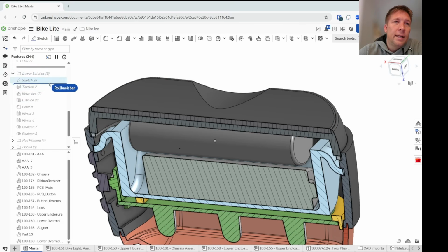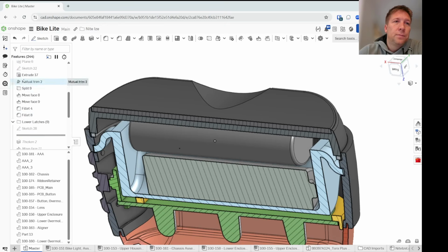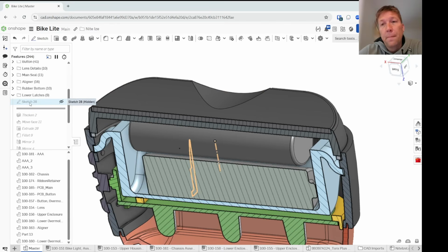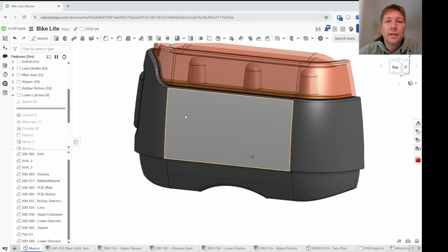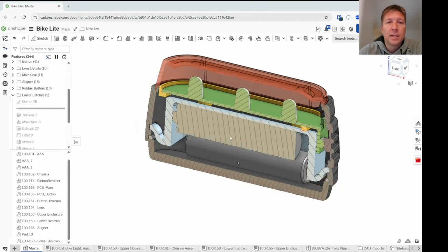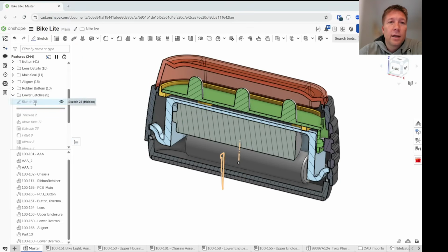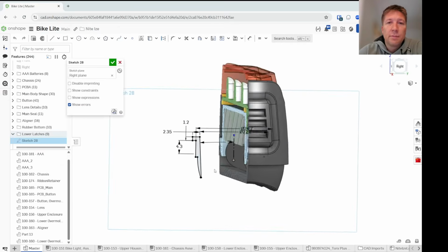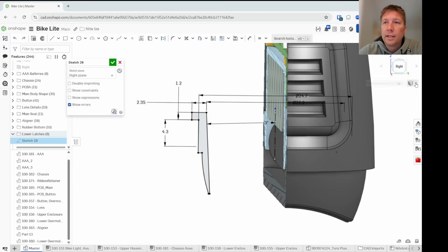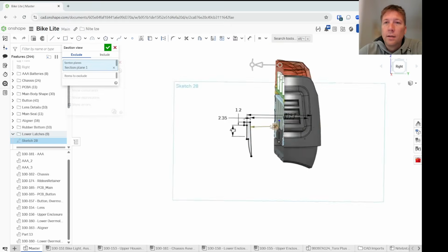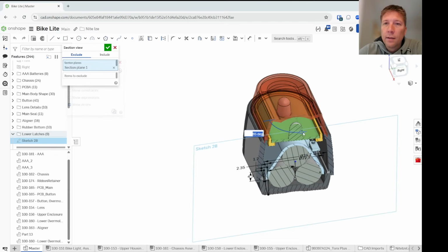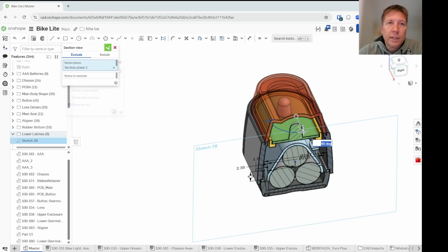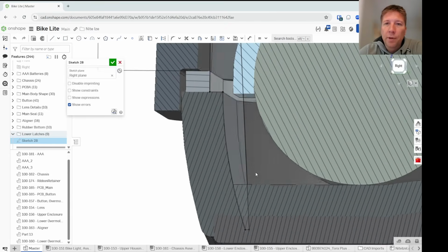Now the lower lid needs to stick onto the lower enclosure. And to do that, we have these small little latches here on the side. So I created this sketch, just taking some dimensions, and I intentionally intersected those sketches with the wall of my part.